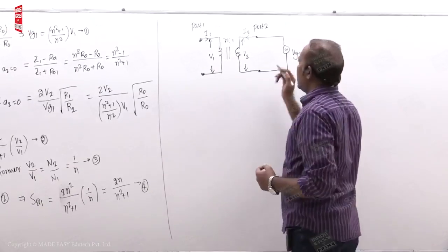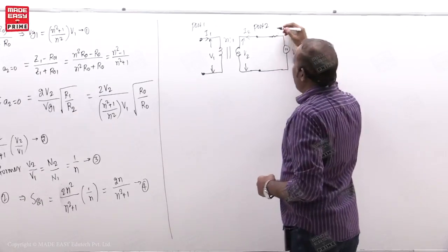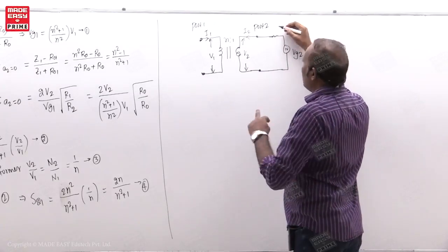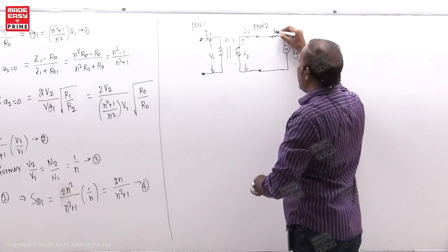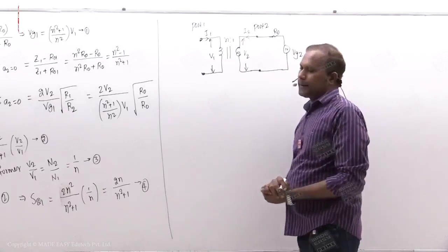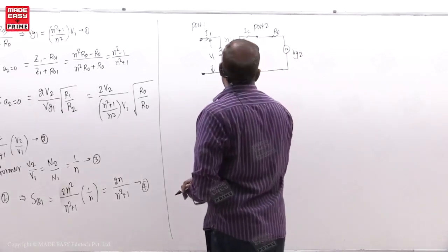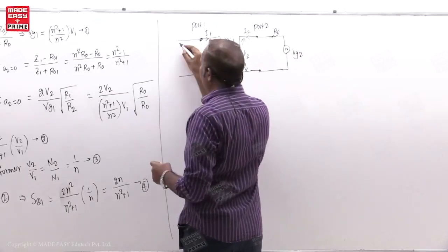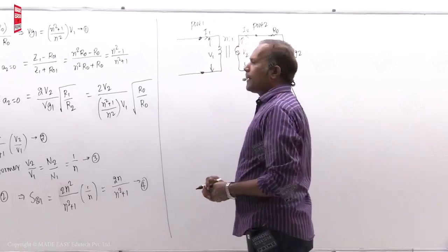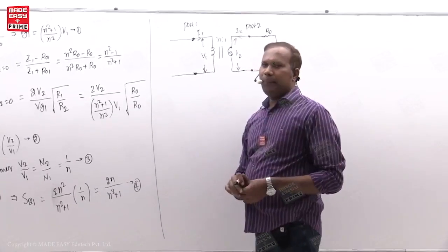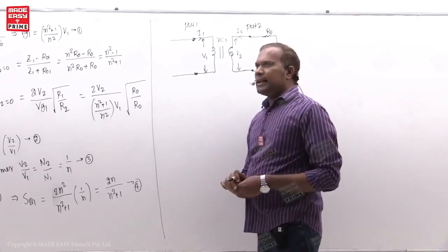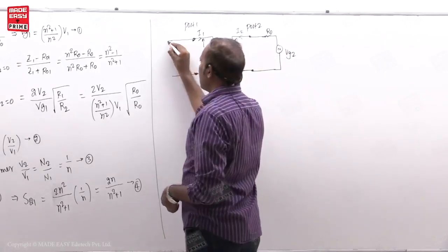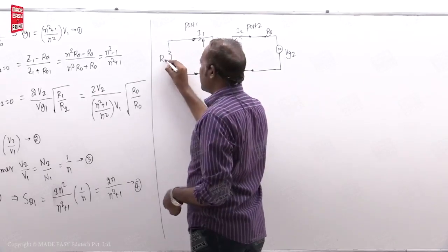You adjust that impedance in such a way that the terminating impedance R2 at port 2 becomes R02. That R02 is given as R0 here, students. Now here some load impedance should be there. That is called R1, the terminating impedance at port 1. That is adjusted to the R01 value. That R01 is given as R0. So connect here R0, students.